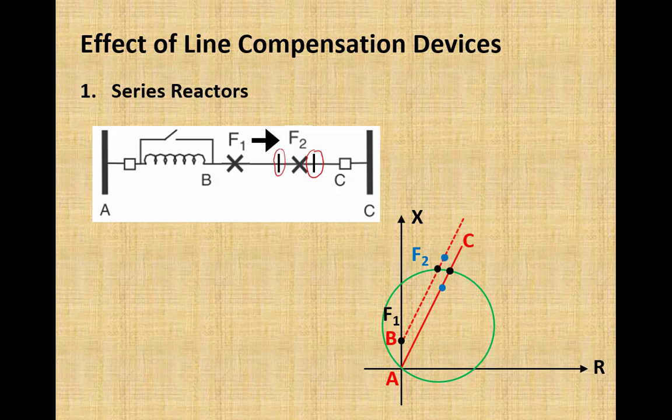Why has it happened? It is due to the presence of this series reactance, and this is known as the relay has underreached. Now, as there is no issue in detection of a fault right after the reactor, we do not need to discuss that. The only thing is how to do the setting to address this problem.